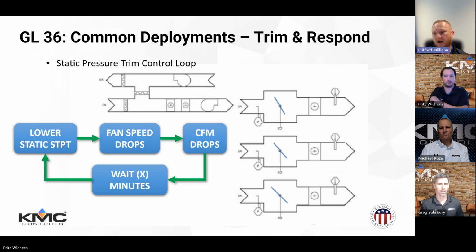On the box, you necessarily wouldn't do it off of box flow demands because hopefully you're maintaining your box flow fairly tight. What I've typically done quite often is generate the request based on damper position. So if the damper position is greater than 95% open, then it generates a request.